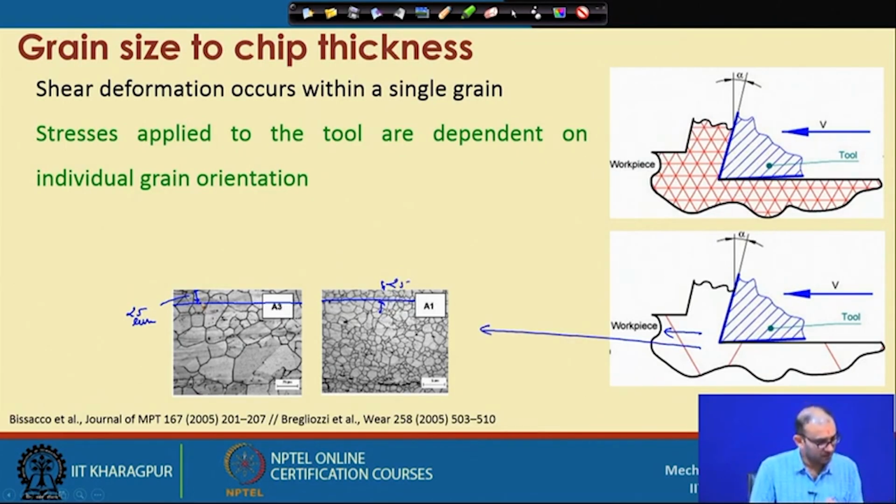Now coming to this part, first this one. Even if you are cutting at a 25 micron depth of cut, you still have a high probability of getting the grain boundary, because the size of the grain is even smaller than what we have seen. So here it is 5 micron. This dimension is 5 micron. So if you consider 25 micron, it will be something like this. In this particular case also you can easily remove the material.